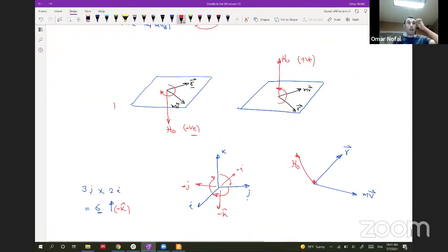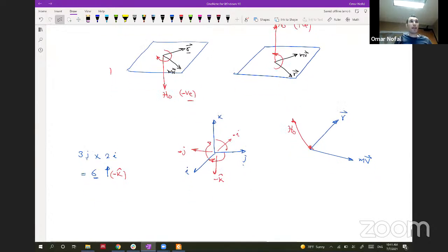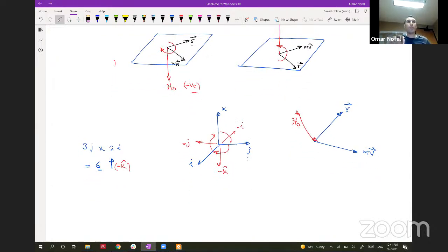All right. Based also on this concept, we can derive what is called the moment of a force. As you know, if you have a point O and a force F here, and you want the moment of F about point O, you basically multiply F by the distance d, so the moment will be F times d.